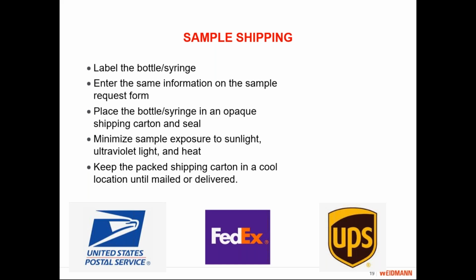A lot of that same information will be on the label, depending on what type of label you use. Once you've got everything labeled, then place your sample container into an opaque shipping carton and seal it. The idea here is you don't want to expose your samples to direct sunlight, ultraviolet light, or extreme heat. If you do that, it will cause the oil to react. Extreme heat will cause it, in some cases, to start producing the heating gases, so you'll have more fault gas than actually was present in your transformer oil from the tank itself. So you want to keep that minimized.